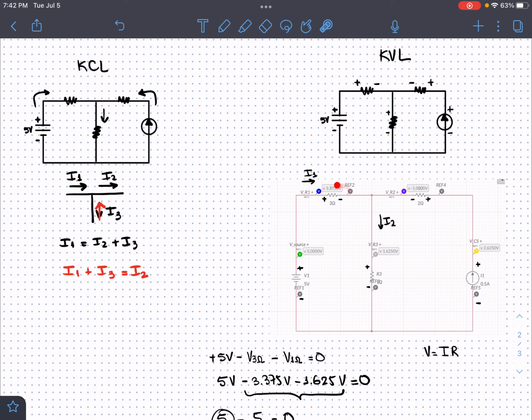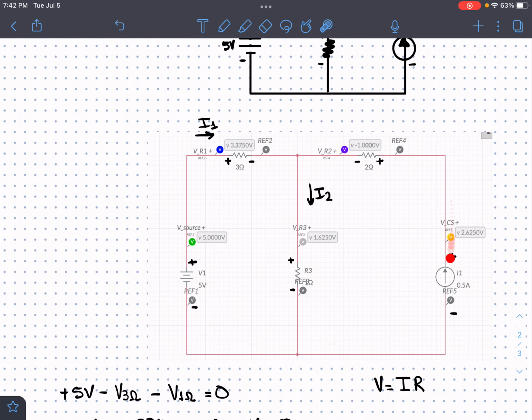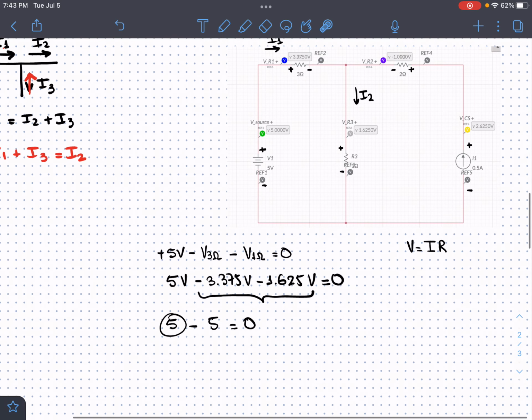This is 5, and then you will add this, and it will be 5. So obviously, plus that voltage minus that voltage will equal 0. You will see exactly the same thing in this other loop. You will see that plus the voltage across this resistor will be equal to those 2 voltages added. So if you go up here, you are going to say plus the voltage across the 1 ohm, minus the voltage across, plus the voltage across this one minus the voltage across this one. Then you will see that that is 0.